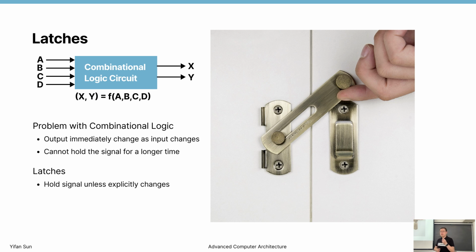In combinational logic, we say every time we put in an input, it will generate some output, right? But different gates may have different propagation times. The transistors close and open at different times. So there must be some transient state within the execution, so that before you reach the final result, your output pins will generate some signals that are considered noise.